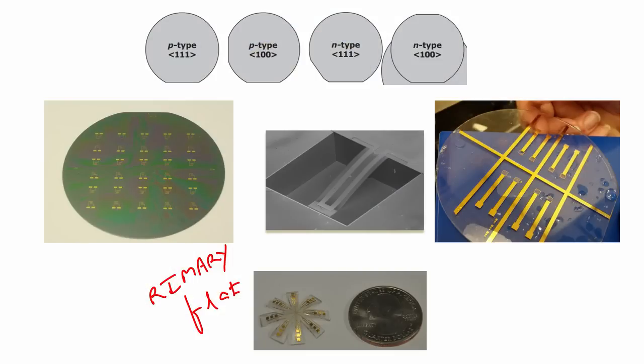A glass wafer you may not have seen, and it is called a wafer because it is thin, like chips. We eat potato chips, potato wafers, they are thin slices. This you see is 500 micron thick, diameter is 4 inch. As you keep on increasing the diameter, the thickness also increases. If you come back on the screen, what I will show you is one wafer which is an oxidized silicon wafer with some devices fabricated on it.